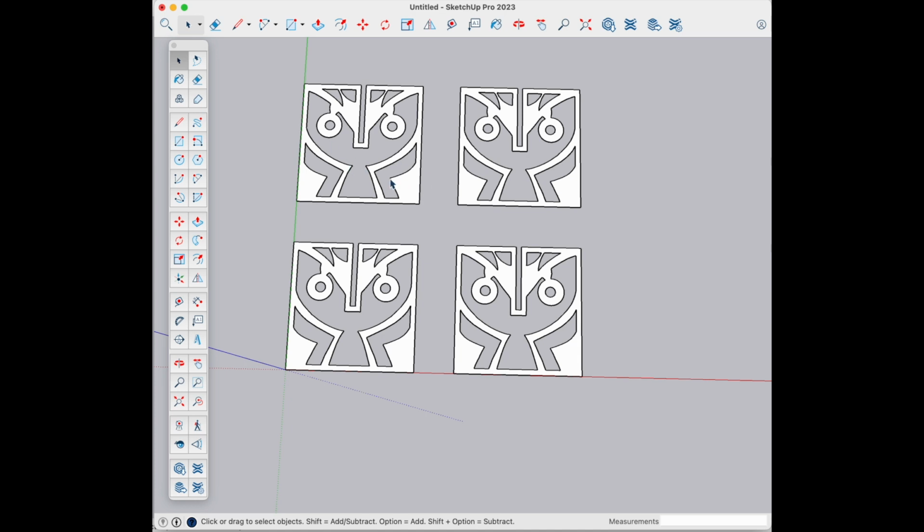Next, we're going to rotate this. So pick one of your designs and you're going to triple click, and then we're going to use the rotate tool to rotate it. The rotate tool is underneath the move tool and it has concentric circles with the arrows on it. Click that and you'll notice that the direction is in the up position, and that's fine. We want to use that.